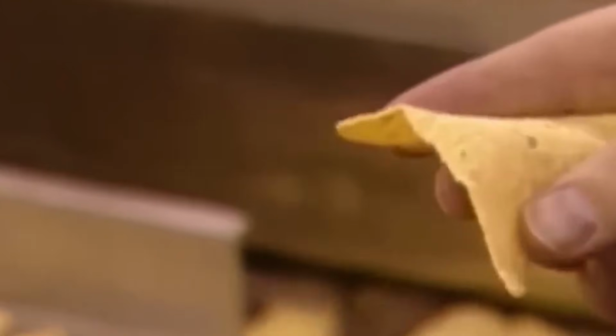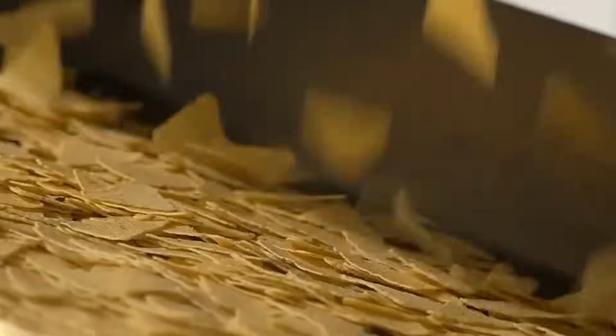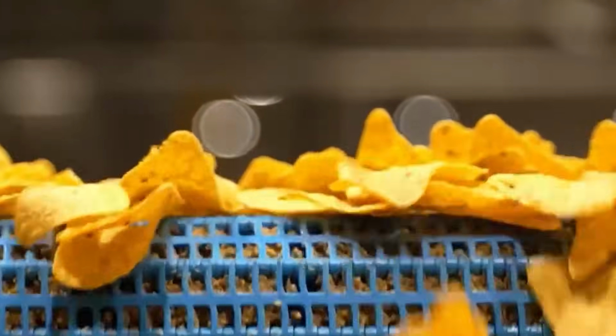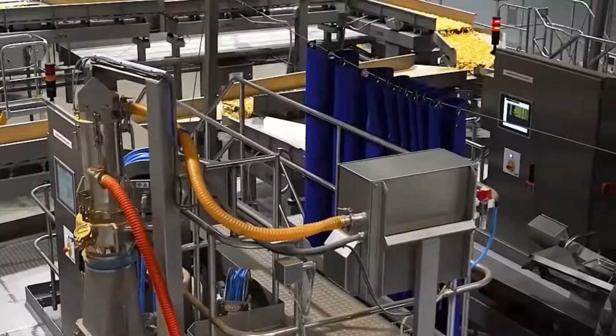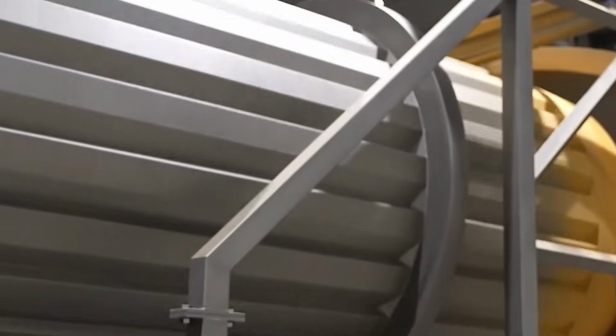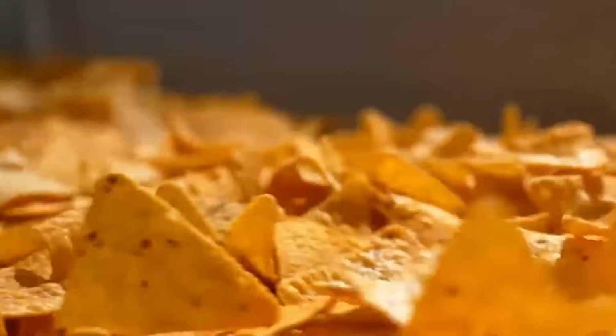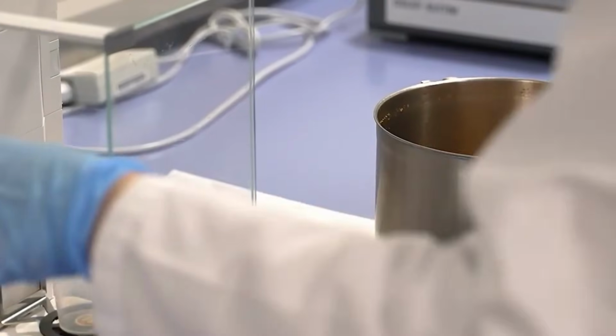Seasoning systems support multiple recipe profiles. Each recipe includes component percentages, feed rates, viscosity targets for slurries, spray nozzle pressures, and pump speeds. Recipes are stored digitally and loaded via the line's control interface. Seasoning is prepared in parallel tanks to reduce downtime between batches and allow flavor sequencing.